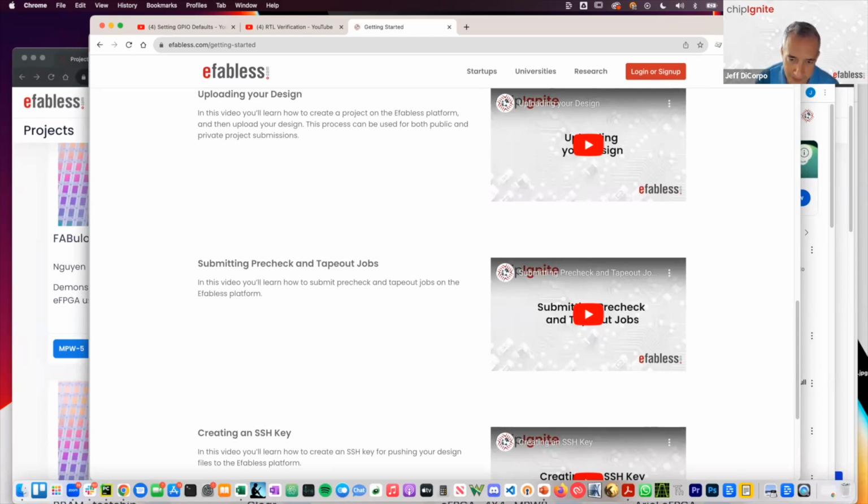After you run make user_proj or whatever your macro is, or the final user project wrapper, within the run directories under OpenLane, there'll be a whole set of reports for the various steps, including timing analysis, static timing analysis. The default is a fairly small set of corners, but the flow is enabled to run a very large set of corners.